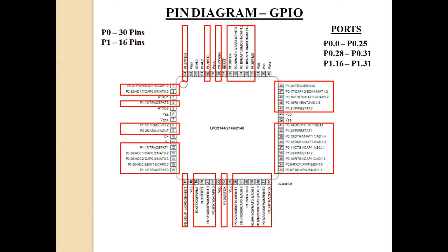So you call the GPIO peripheral a GPIO port. What do you mean by port? Port in this scenario means a collection of external pins. Why are you using them? What is the use of these pins? Through these pins you are going to interact with the input or output devices. If you want to connect an LED, you need to connect it to a pin. If you want to connect a switch, again you need to connect it to another pin. So the collection of external pins shown in red color is known as the port.